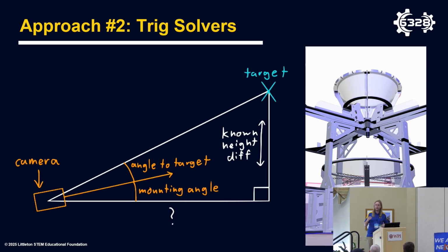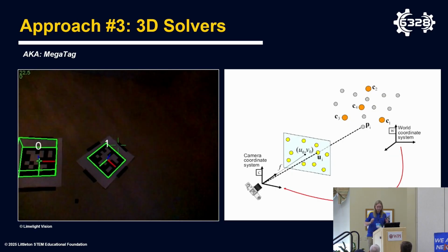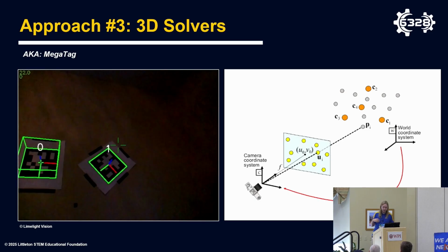The main limitation is that this requires a height difference between your camera and the target. So one is significantly above or below the other. This also relies on having a very accurate gyro position. That can be a major disadvantage at times, since even the best gyros can and do drift. If you want to see a demonstration of that, try running an FRC robot into a wall at full speed and see how your gyro likes that. The results will not be pretty.